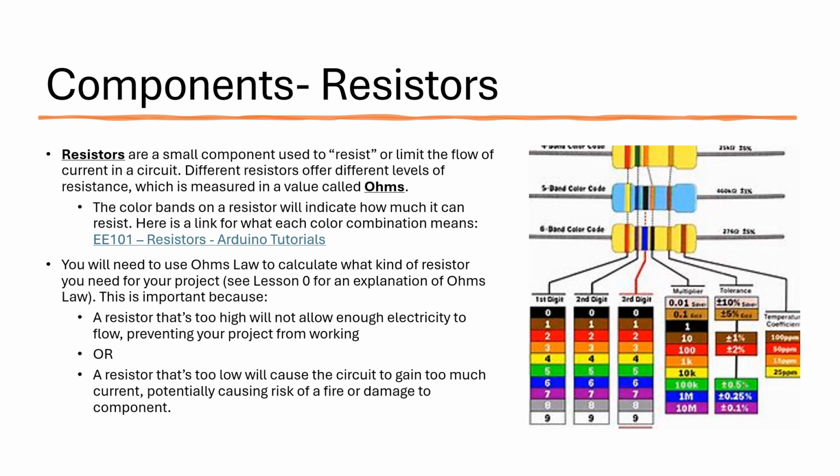Ohm's law is a scientific principle describing the relationship between voltage, current, and resistance. The principle explains how voltage depends on the values of current and resistance, which are represented through the equation V equals IR. Alternatively, the equation can also be written as I equals V over R, or R equals V over I, depending on the value you need. In this case, we'll stick with R equals V over I since we need to find the resistance.